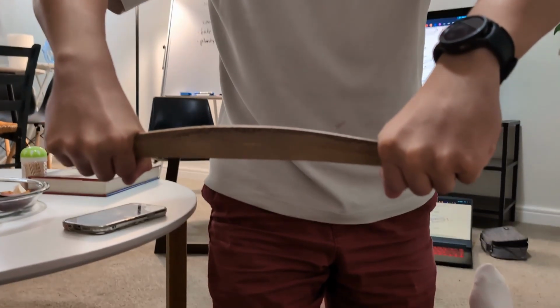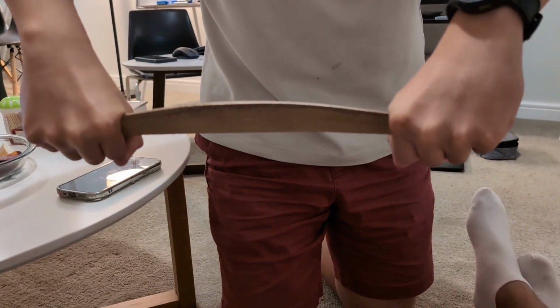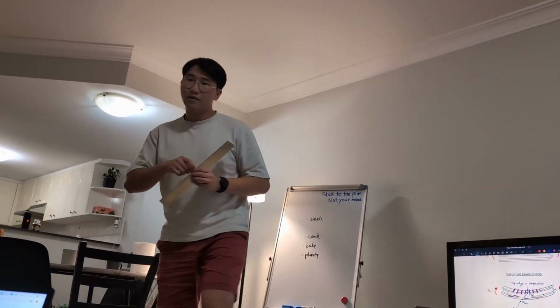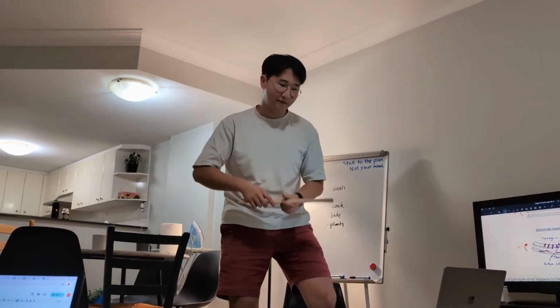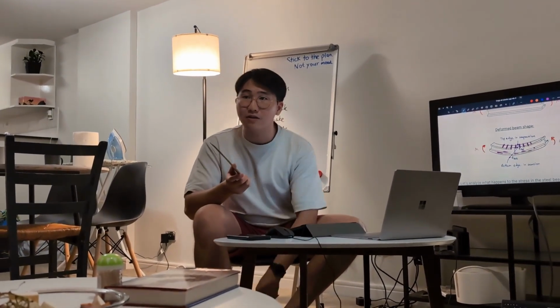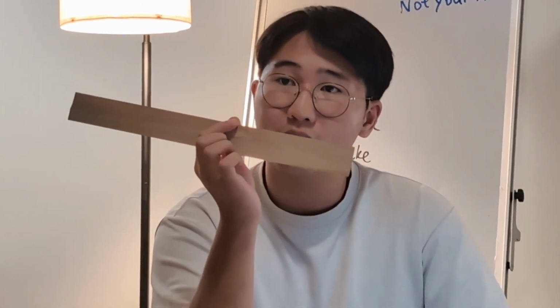So now I'm racking it. Oh, it's kind of snapping. Do you see what's happening? What's happening in the top flange? It's buckling. Is it in tension or compression? Compression. Exactly. So the compressive thing that we learned, where compression causes buckling, still happens, but only at the top fibers. But the bottom, what's happening?